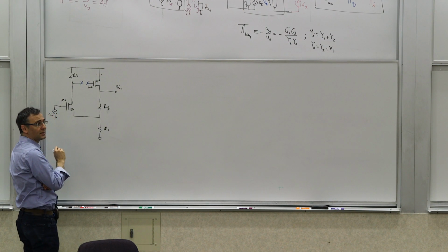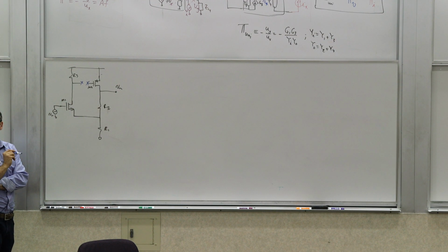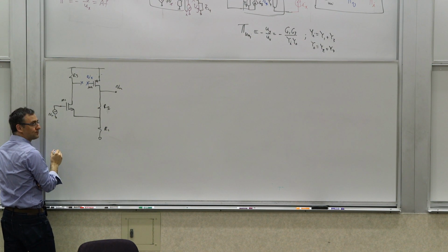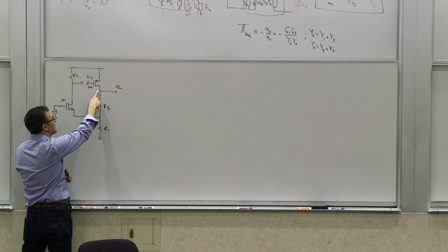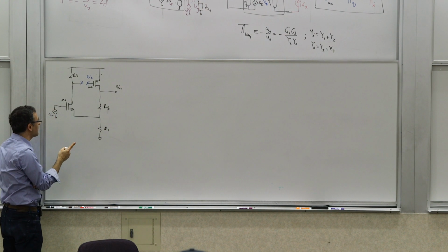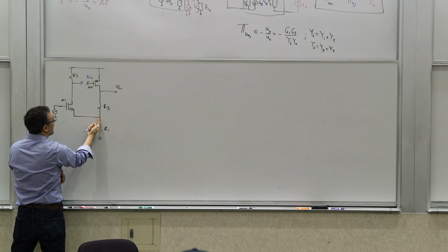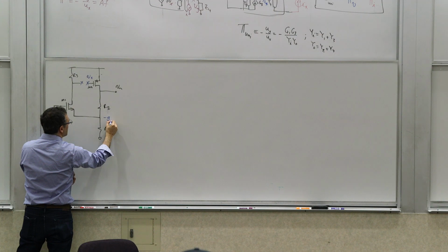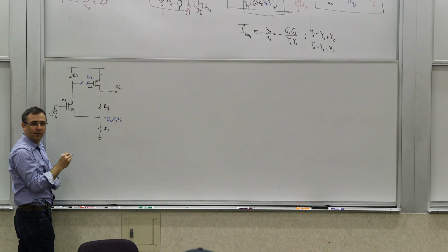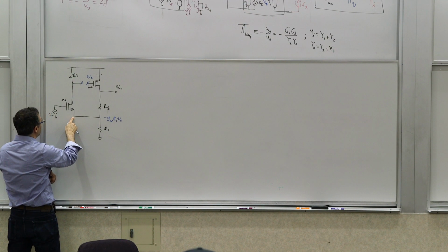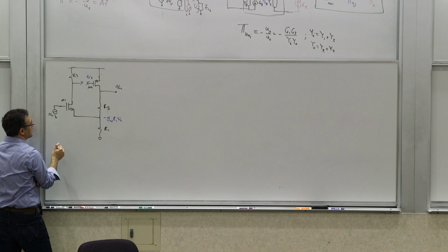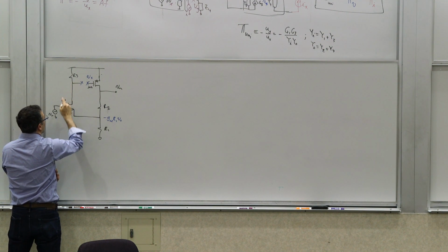So we need to calculate two quantities, the voltage loop gain and current loop gain, right? The voltage loop gain. If we apply voltage Vx, what do we get? Well, if it's Vx here, this current is going to be Gm2Vx, right, from a small signal perspective. That current is flowing through R1, so this voltage is going to be negative Gm2R1Vx, right? And now that voltage is basically reflected here with a gain of this stage, which is going to be now Gm1 R3.